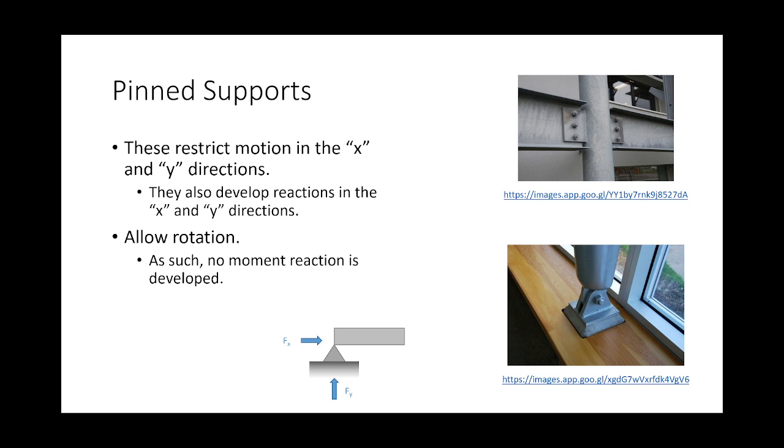The reason that I-beams are configured the way they are is because whenever you're trying to design that shape, the idea is to get as much material away from the center of gravity or the centroid of that I shape as possible, which is why you have a beam and you've got 2 plates that are sort of way far out in space. So the idea from a mechanics of materials perspective or mechanics of deformable bodies perspective is that